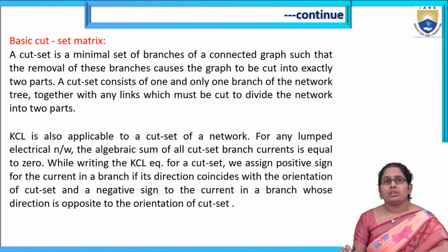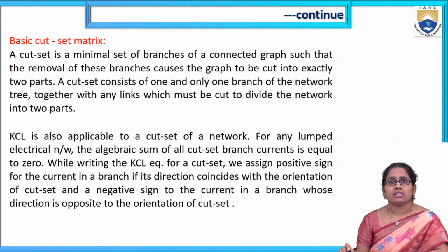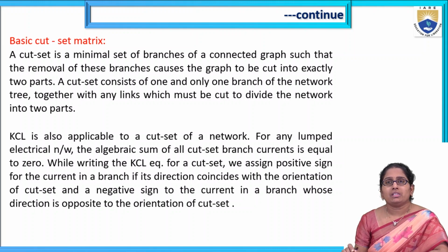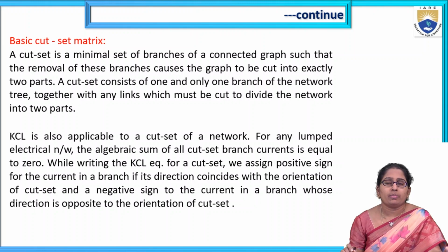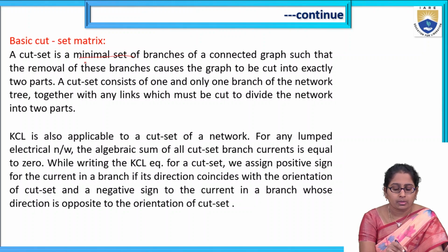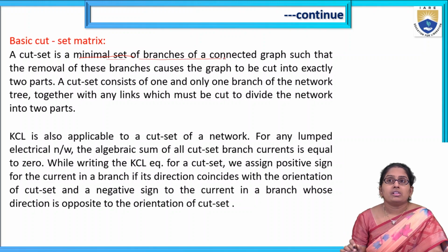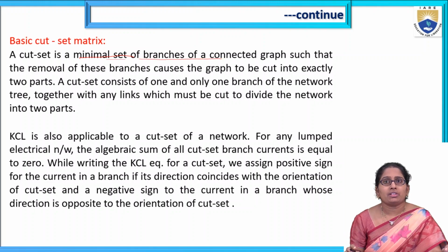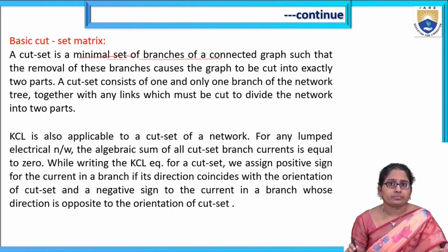Basically, a cut-set is a minimal set of branches of the connected graph such that the removal of these branches causes the graph to be cut into exactly two parts. If we remove those branches, the original graph is divided into two parts.